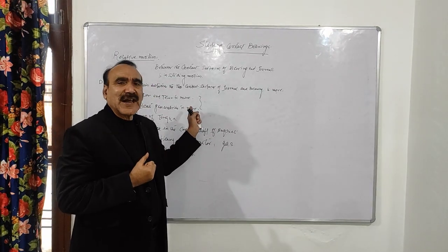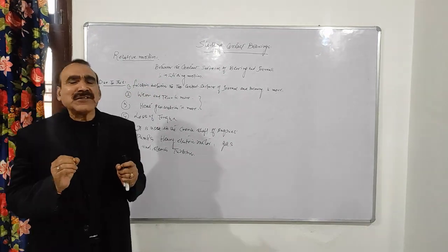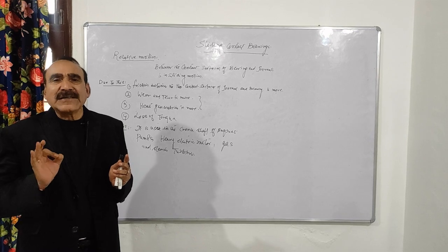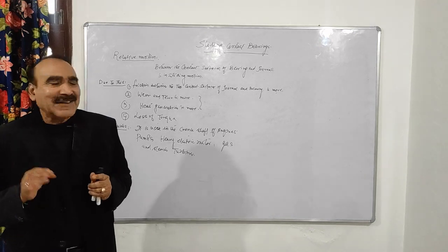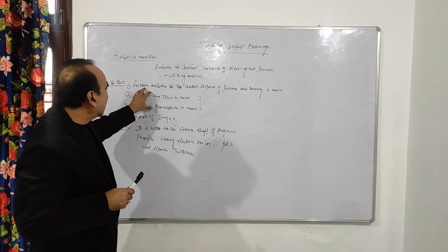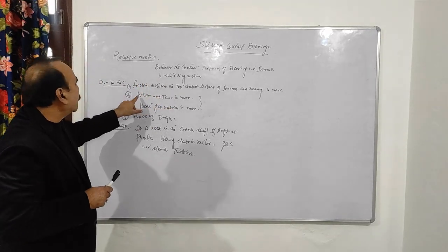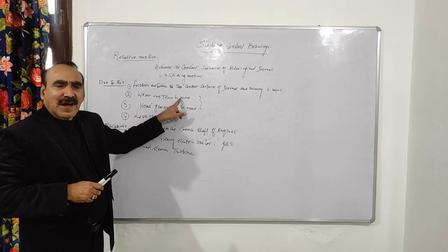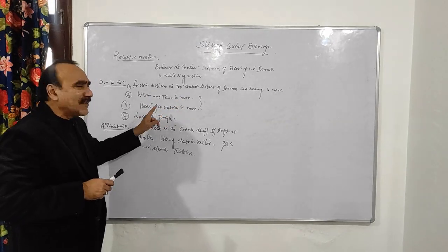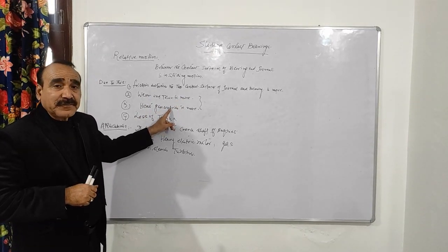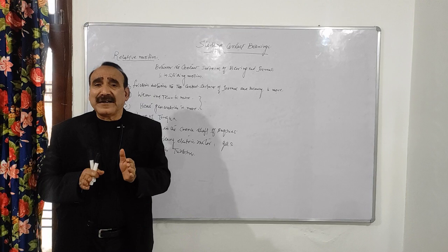In case of this, there is a sliding motion, and when there is a rolling motion, the friction is almost nil here. In case of rolling contact bearing, I will say friction is almost nil. These things depend upon the friction, so when the friction is almost nil, wear and tear is almost negligible, heat generation is almost negligible, and loss of torque is not there. So this is the difference in the rolling contact bearing, right?